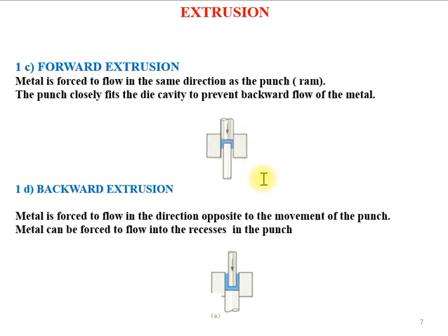the material needs to flow through some opening space. In this case, the opening space is the downside. However, there is a mandrel placed here. The mandrel is nothing but a solid object. Consider it as a solid bar. Fine. So when we apply the compressive force onto the billet, the mandrel having a smaller size than this die opening, the material once compressed will flow all around this mandrel. And once the process is done, you lift the ram, you remove the mandrel, and you will get a hollow component.